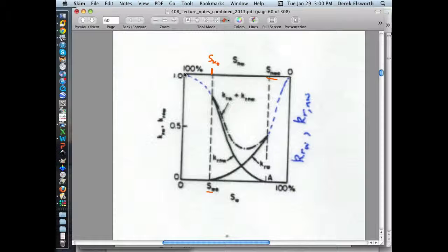They do have to join up with these points here, but this is a difficult area to make measurements with because you can't really get saturations to change very easily in there without evaporating fluids, typically. But sometimes these curves are shown with this cutoff, but they do have some values that go there, and so you can either do it by extending the curves like we've done here in the blue, or you could choose some other arrangement. You'll notice also that the relative permeability curves are always between 0 and 1.